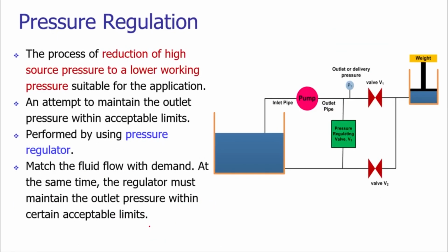In applications of hydraulic systems, many times we need to hold a weight. For example, the hydraulic clamps. In hydraulic clamps, continuous pressurized fluid is to be applied. But that continuous application leads to an increase in the pressure of the system. The pressure may be more than the operating pressure of the system.